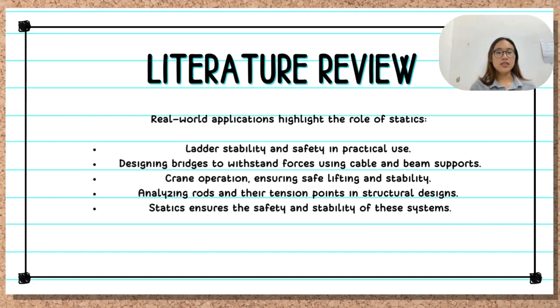Last but not least, a uniform rod suspended by a rope. A crane arm resembles a uniform rod held by a cable at one end. Statics helps engineers analyze forces acting on the arm and cable, ensuring safe crane design. This includes calculating the maximum load, optimal arm angle, and cable tension.